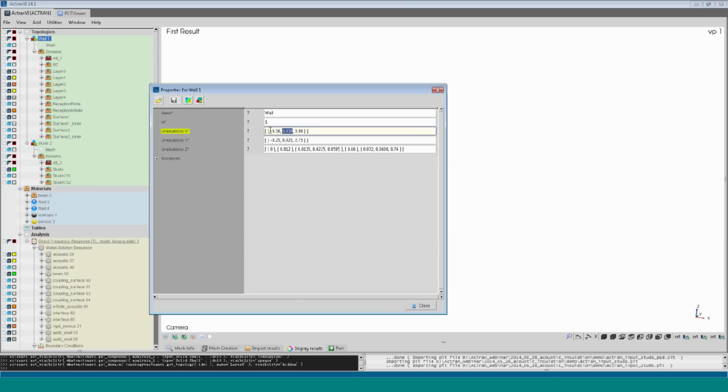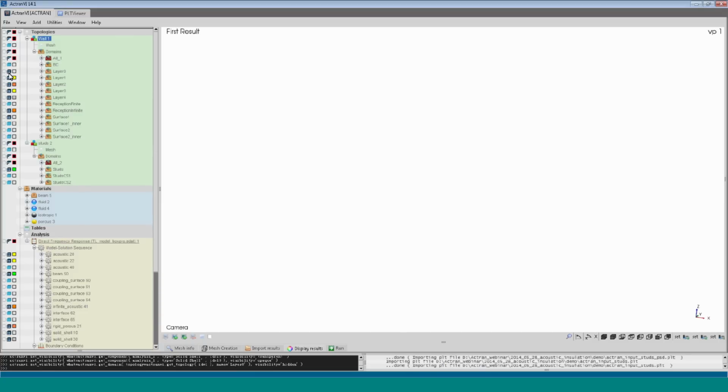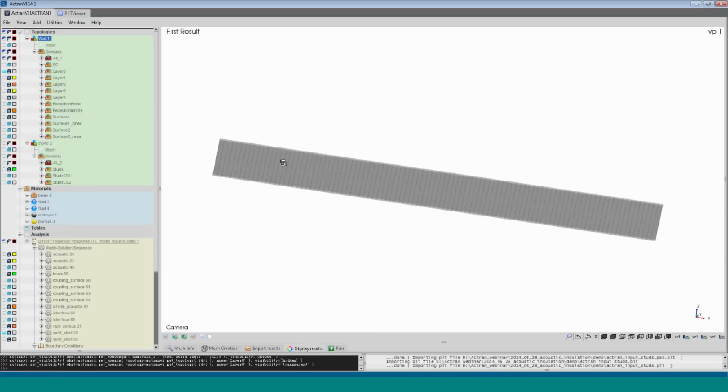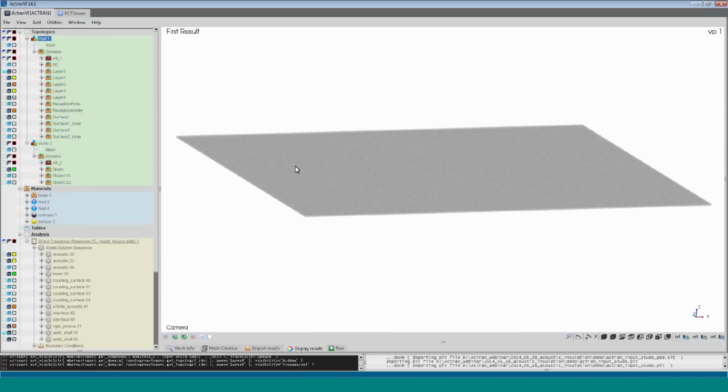So here we define a series of vertical grids along the X direction, and in the same manner we define these grids along Y direction and Z direction. On these grids we will define later on different regions for different parts of the model. The model is already prepared, so I will just walk through the different parts to illustrate the modeling process.